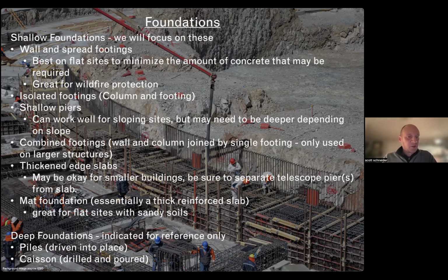Mat foundations can be really great, as I mentioned before, when you have sand. In fact, they were actually invented in Chicago for the Auditorium Theatre, if anybody's ever been there. They were on marshland, and they built a giant mat slab to distribute the weight of the building.